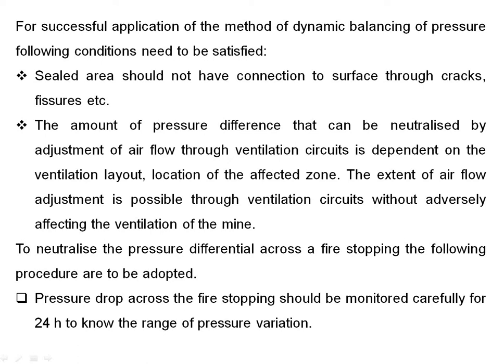I told you earlier, to neutralize the pressure differential across fire stoppings, 4.8 meter stoppings are there. In between those stoppings there is a fully concrete stopping, and in between the stoppings a sand stacking will be there, or sand as well as fly ash packing. That will be the fire stopping, and the pressure drop across the fire stopping should be monitored carefully for 24 hours to know the range of pressure variation. Generally one pipe is there for the water percolation, also a U-tube is there, and no other pipes are connected, but an air sample point is there, so it can be monitored over 24 hours to know the range of the pressure differences.